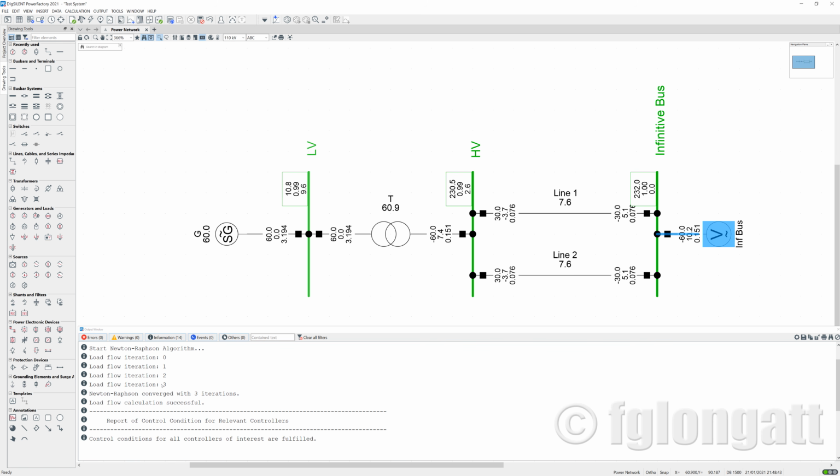And in this case, when we finish here, we have the load flow, okay? Right now we have, let's see, we have the proper load flow. How do we know that this is properly working, okay? First, let's check the logic. The basic logic here is, here the voltage at the bus bar should be 1 per unit at 0 degree. Perfectly fine. You can see over there 1.0, and in that case you can see 1.0, okay?